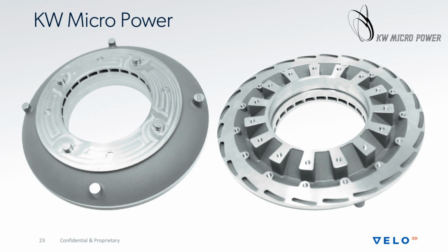But focusing mostly on the geometry, what you've got here, if you look on the left, is all these intake ports for some sort of impeller, which puts a fluid in and turns it around in a sweeping pattern. If you call this upside down, more or less, you have the entrances in the middle but the exits on the outside, and they sweep at very low angles. We're talking about down to 10 degrees or even less in some cases.